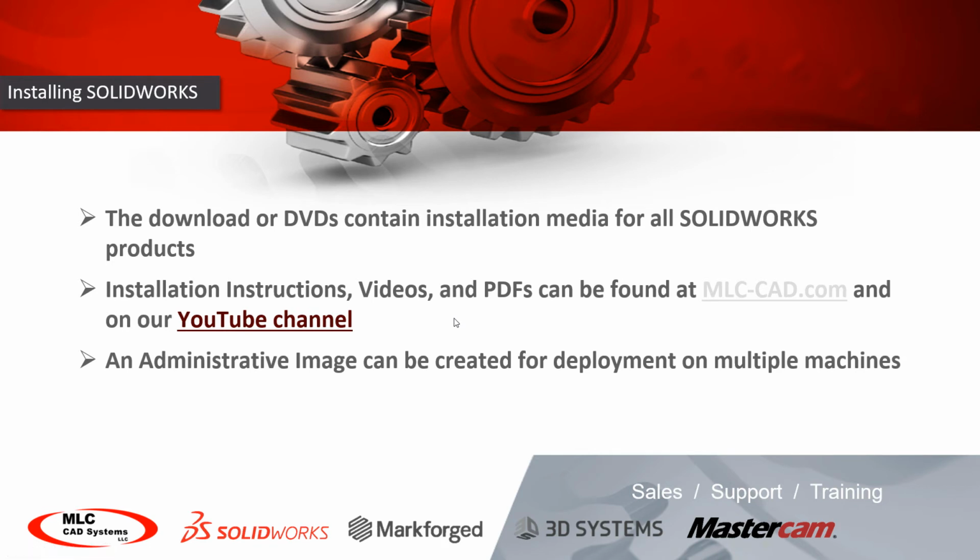I'd like to point out that you can also create an administrative image. If you're going to be installing SolidWorks on, say, 20 different machines, you might want to set up your installation just once and be able to automatically deploy that. That can be done through an administrative image using the same installation manager.